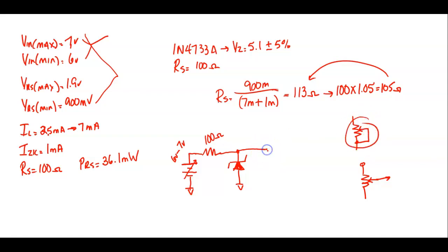So what I'm going to do is use a 100 ohm resistor so we don't create a short circuit, right? And then I'm going to use a pot wired as a rheostat. So now we can adjust the current. The maximum current we could get is if we let that guy drop all the voltage. Now, we got to measure current. So how do we usually measure current?